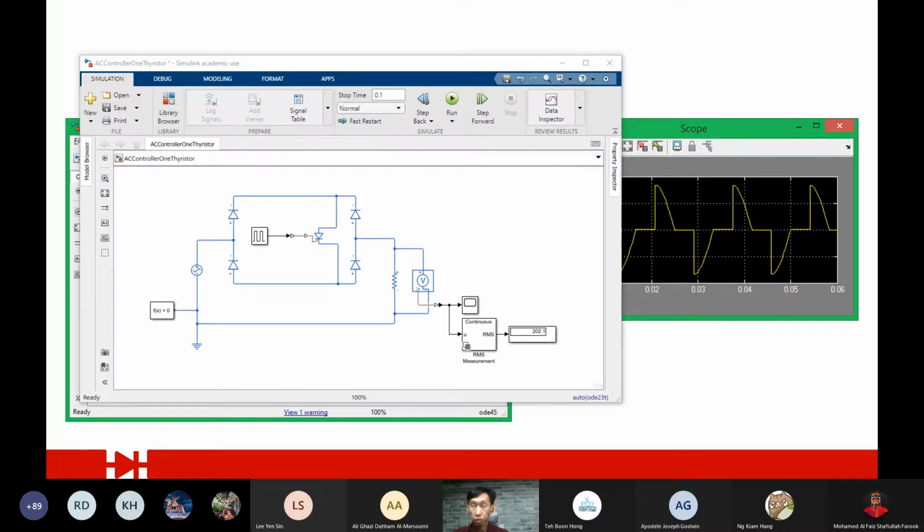It shouldn't have any difference as long as, if your source is 60 hertz, your pulse generator needs to be 120 hertz. If you use 50 hertz again, it will happen just like what I showed you when the phase is out of sync. You will have the out of sync problem.